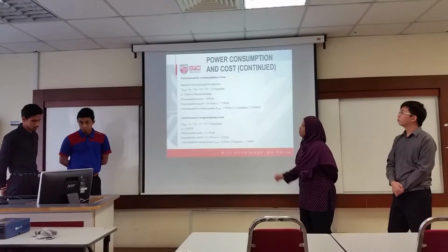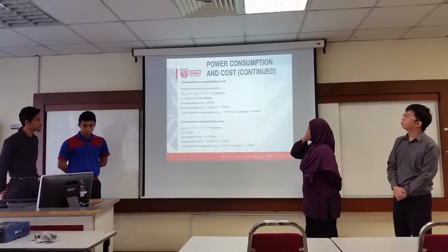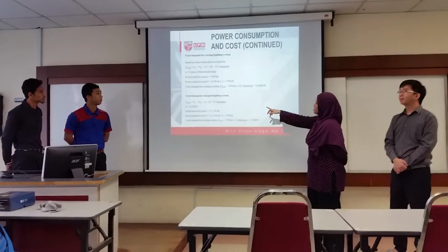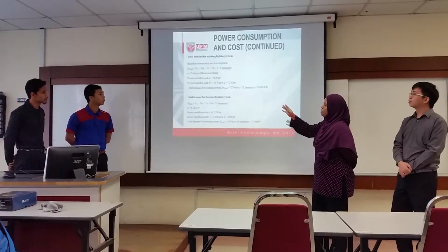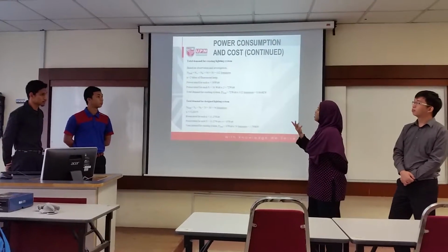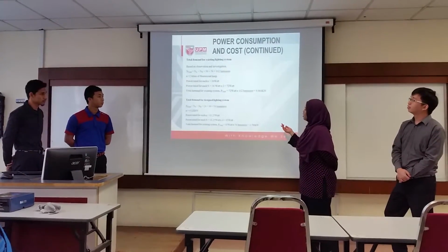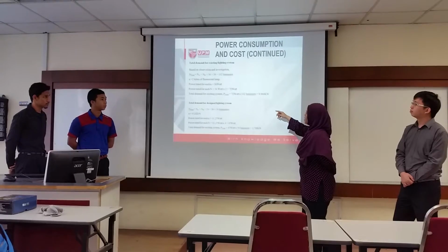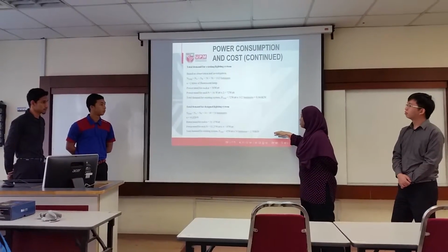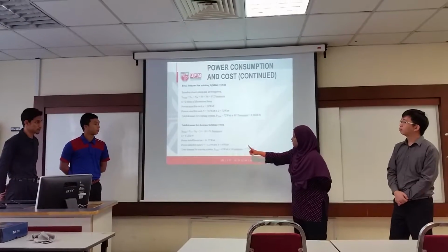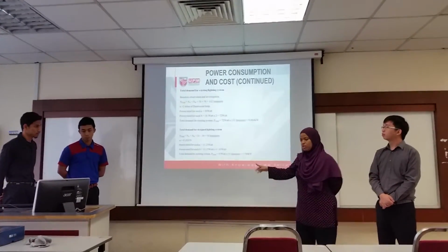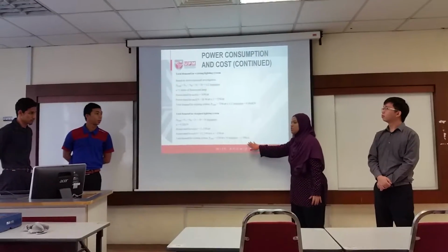Okay, so this is how I calculate the total demand. For the total demand for the existing system, we calculate the power rated for each, capital N, times the total luminaire, and we have the power. Same for the total demand. The power rated is 45 watt, so we times 54 luminaire, we will have 2.7 kilowatt.